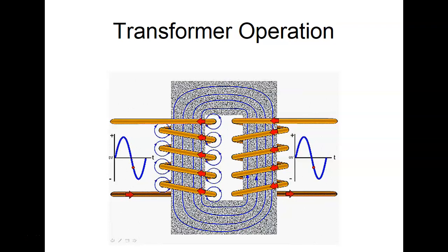So this is a transformer action. Notice that when the magnetic field goes out of here, current flows this direction, and current flow over here is in the opposite direction. So here it's coming out, here it's going in. So on a transformer, if we hook them up exactly the same, then the output will be 180 degrees out of phase from the input, which usually means nothing to us, right? So on some transformers they'll put dots on them, which say if your output phase needs to be in the input phase, then these are the ones you need to use for L1.